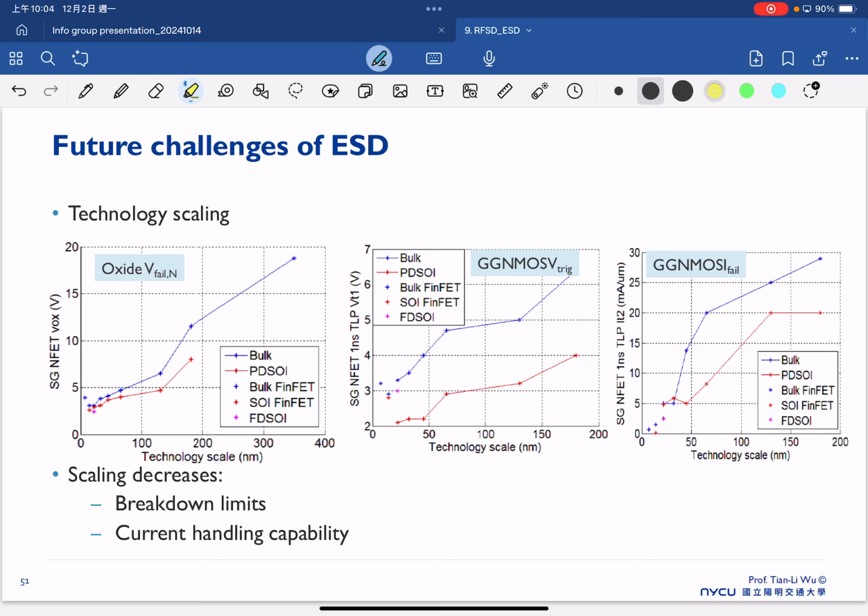that will also cause a huge current divergence. And once we move to the advanced technology, we also suffer from the ESD issue getting worse and worse. One of the issues is, for example, that the oxide can fail more easily, because we try to fabricate devices with a very thin dielectric, so the oxide has a very small breakdown voltage. Then we need to place a lot of ESD protection, because the ESD voltage is not scaling.